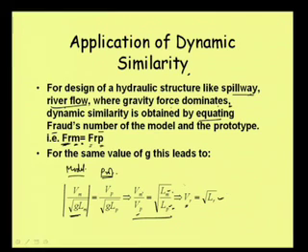So, this is a very important relation that we are obtaining, that is, the velocity ratio is equal to the square root of the length ratio. That means, suppose we are constructing a model and we are trying to maintain Froude number similarity. Then in the model, first we are taking a length ratio, and according to the length ratio we are sizing our model, means we are shaping the model and maintaining the length ratio that we are deciding. Okay. So, that way we make the model.